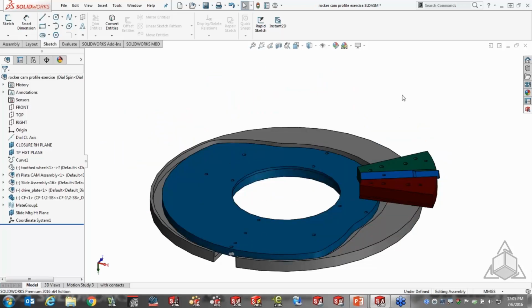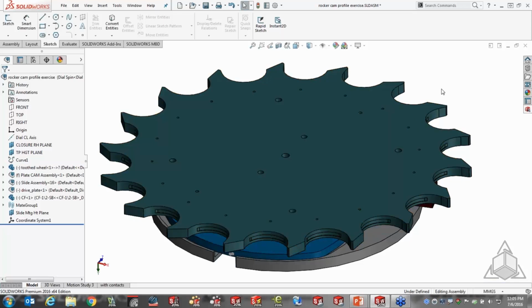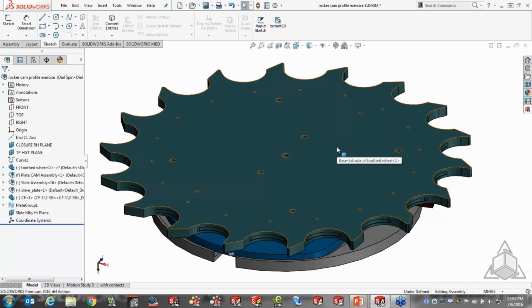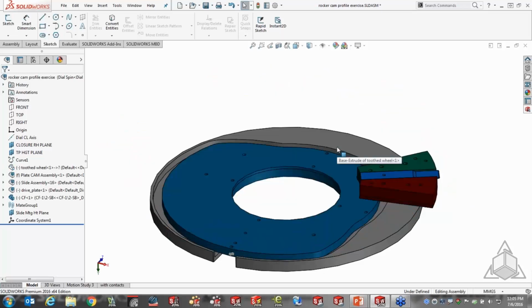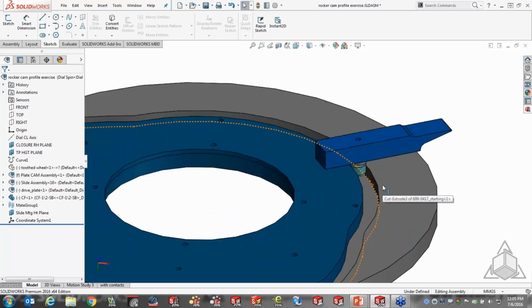There is another option, which is Ctrl+Shift+Tab. That will show you all hidden components and allow you to select the ones that you want to show. So for all the mate presentations today, I'm going to be using the ability to tab a lot in order to get what I want showing available to me.